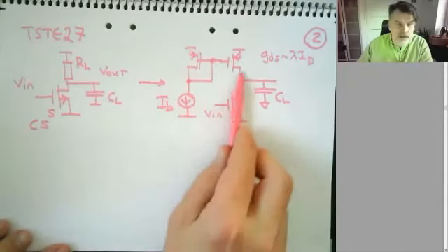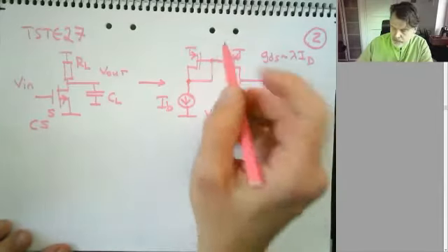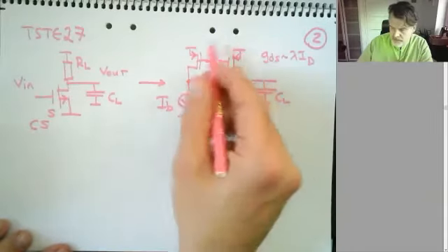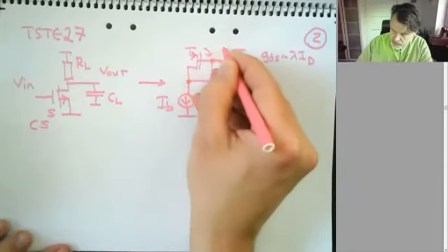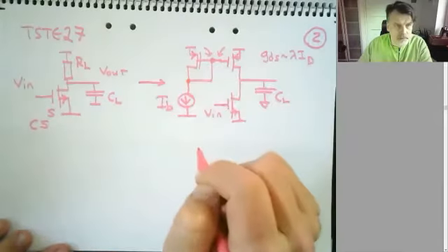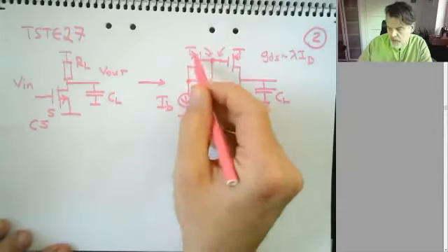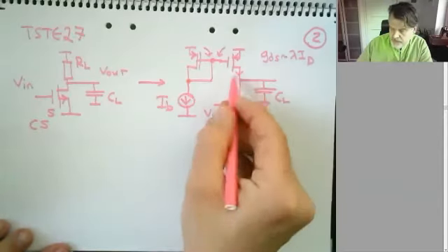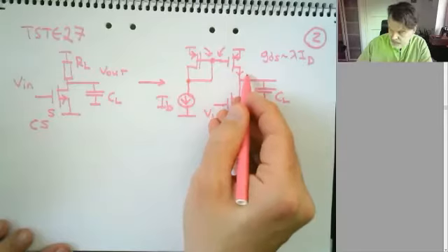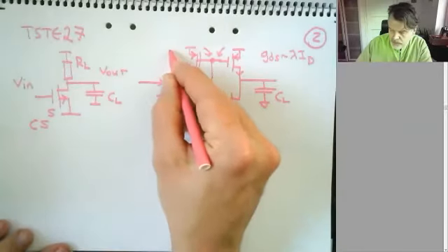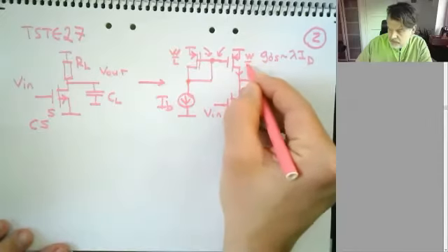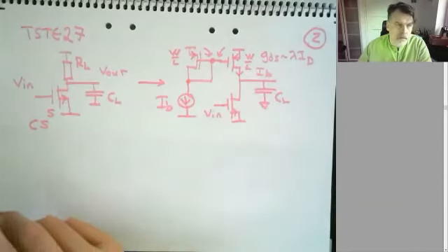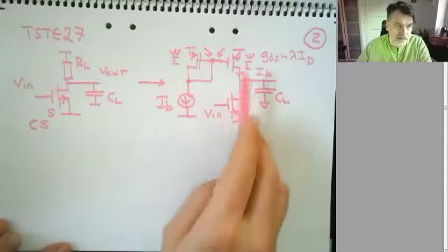So the nice thing here is that I get rid of design parameters. I don't really need to care about VF, W, or L for these transistors. If I have this current mirror structure, because I have the same source-gate voltage on the PMOS transistors, and they have some sort of physical size ratio, the current more or less is a factor times this bias current on the output here. So if the mirror ratio is 1:1, they have the same W/L on both sides, and the current coming out on this side is also IB.